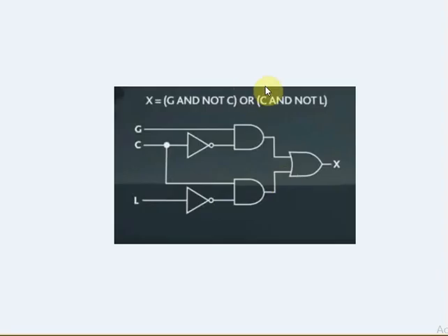We just see, right, here OR, this side branch, this side branch. Then to fulfill the condition, how to input these signals. Right? If they say gas is okay, carbon monoxide okay, you feed directly. But when carbon monoxide is not okay, only then you should get 1 here. So it is indicated not okay means 0. So some circuit is there, if carbon monoxide is not okay, it will feed 0 to this. Then we need to make it 1 here, no? To make X equal 1.